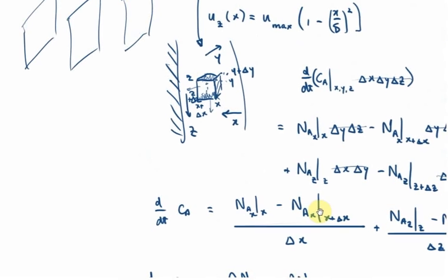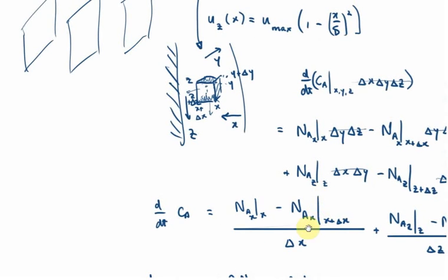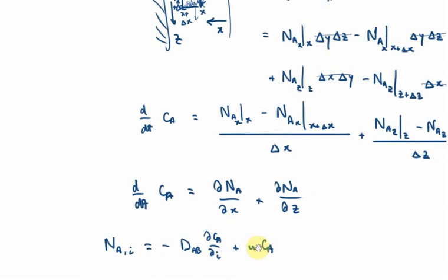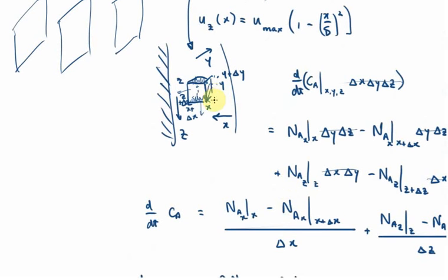And then if we look here at these two possible fluxes, in the Z direction, clearly the majority of the flux is due to the film falling. So simply because this liquid is falling and carrying down with it component A, the major flux contribution is convection.